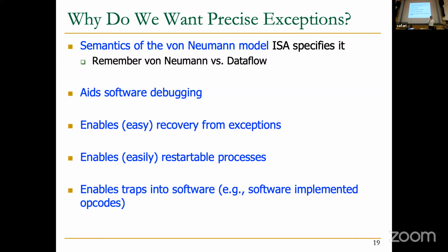And this exception is going to take me to an exception handler that's going to do exactly the multiply using shift and add, basically, right? And then you're going to return from the exception and get the value. That's perfectly possible. That's actually done with complicated instructions. Multiply, of course, is present here. But for example, you may have a floating point operation that you don't want to implement in hardware because hardware is costly.